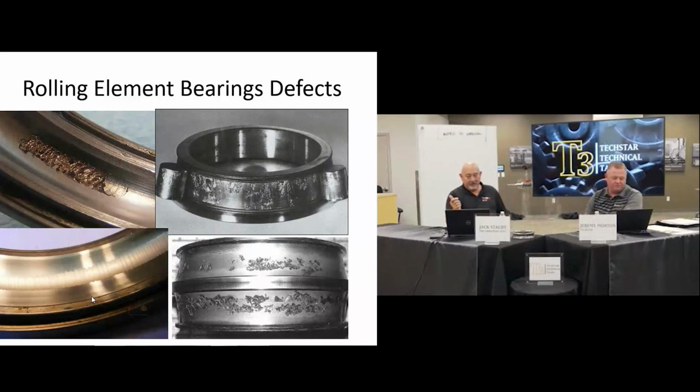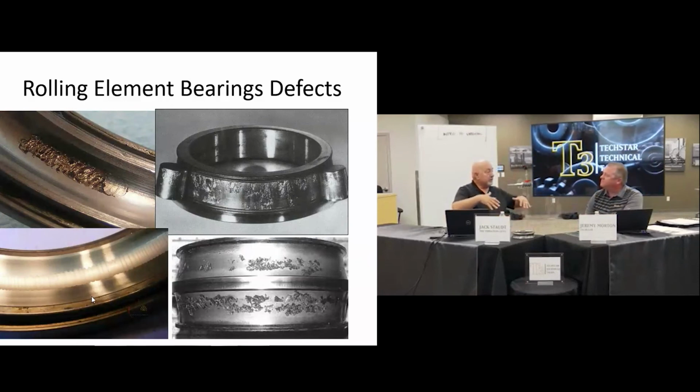That's interesting. And another cause that we see a lot is false brinelling. False brinelling is where, for example, you have 2 electric motors driving pumps, and they only run the A, they never run the B. But there's residual vibration coming through the base and everything.